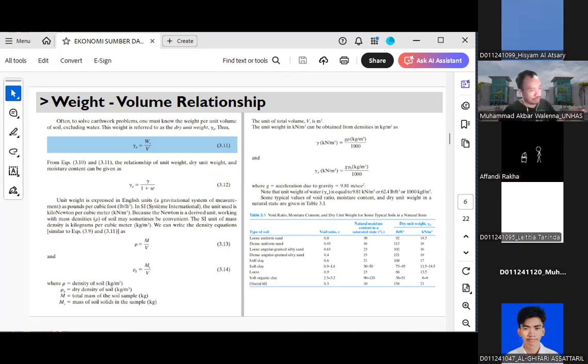So we have the reference point in the lab, and we compare that with what we can potentially achieve on the site. That gives you an understanding of the amount of control we can have over the soil in relation to compaction.